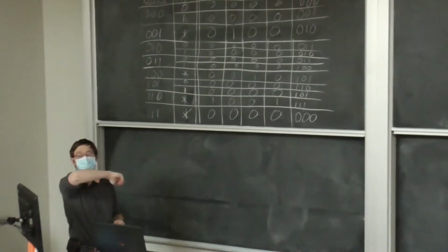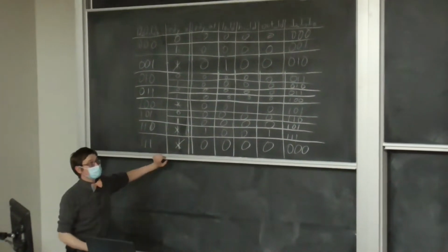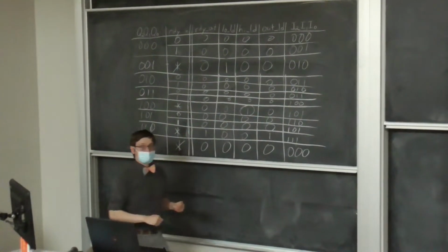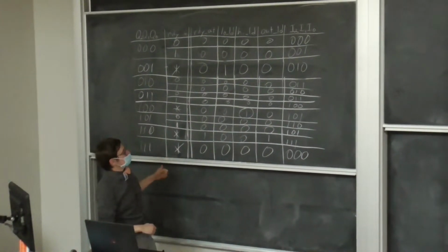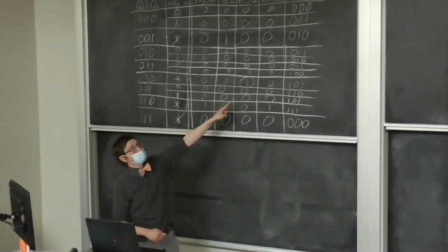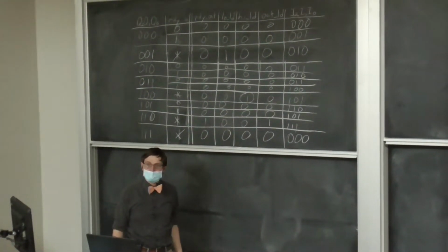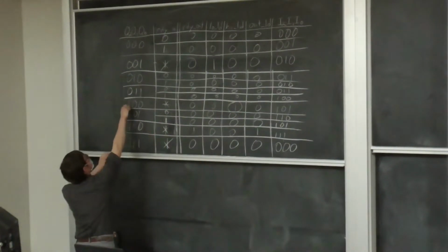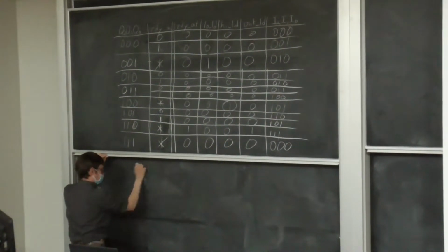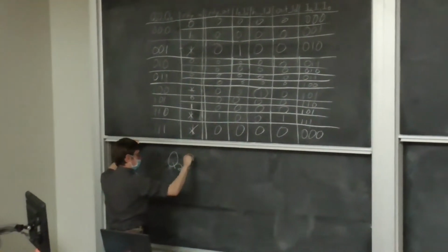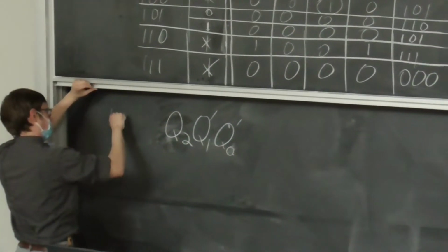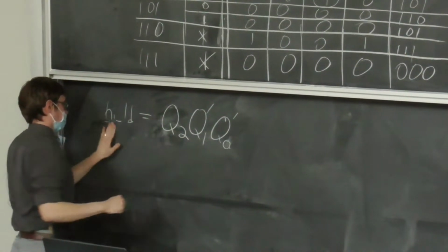So, let's do one of the easy ones. Let's do one of the registers. Actually, you shouldn't even need a Karnaugh map to determine what the condition is for this in terms of inputs. What's the condition for a high load in terms of the inputs? What's the equation? You follow it across, right? Q2, Q1 not, Q0 not, and that's high load. Right?